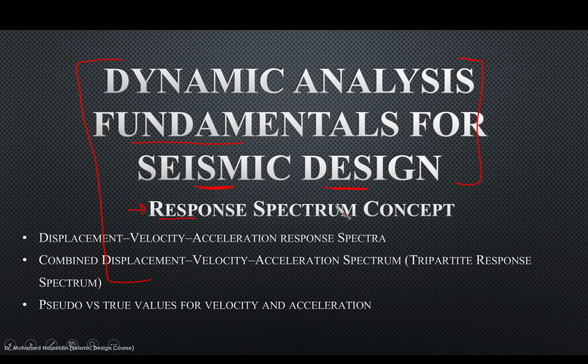and we are going to talk today about three different, important points. The first one is going to be the displacement, velocity, and acceleration response spectra. The second, I'm going to talk about the combined displacement, velocity, acceleration spectrum, which we call the tripartite response spectrum. And then I'm going to talk about pseudo versus true values for velocity and acceleration. These are the main topics that I'm going to handle today, and I hope that it would be easy for us to understand.